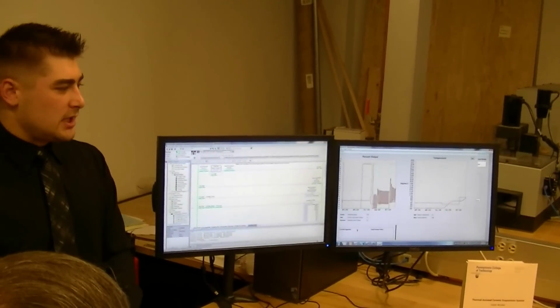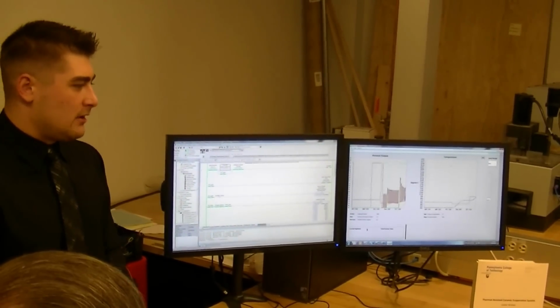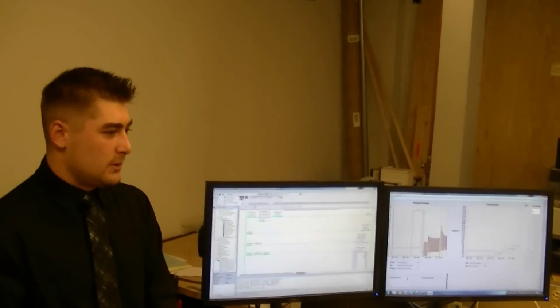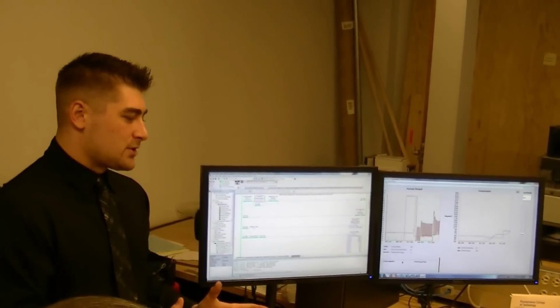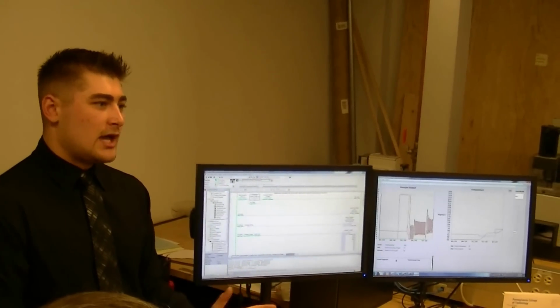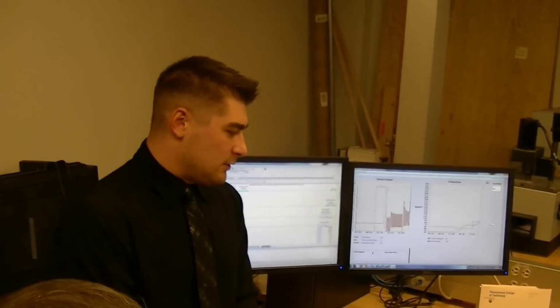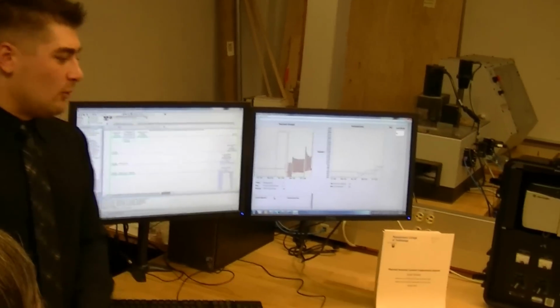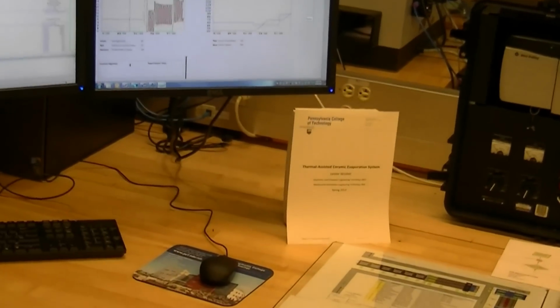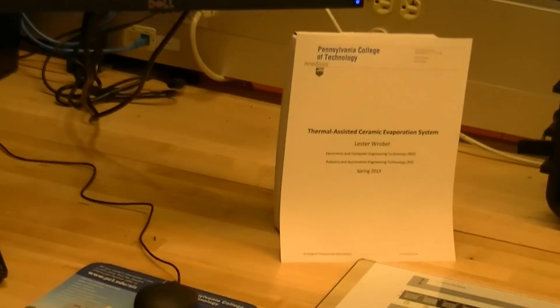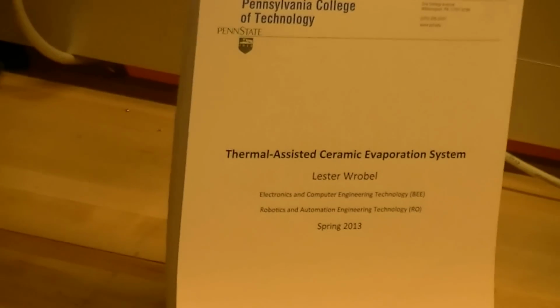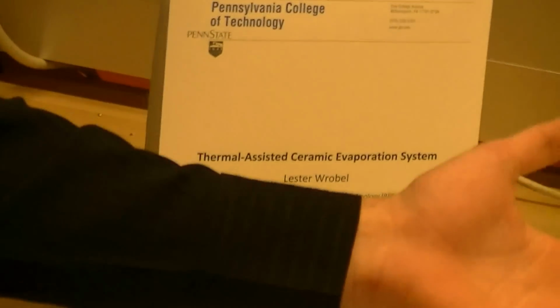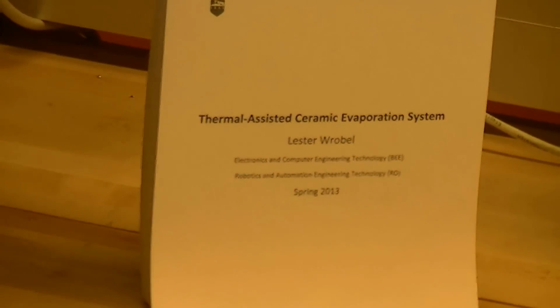We have a little bit of everything in here, and from the ground up, even from the design aspect all the way to the final implementation, every piece is very crucial off of good engineering from the start. As you all know, I'm sure, if you don't have something as simple as a block diagram from the start, you might have someone coming to the system to troubleshoot, and they won't know what the system's supposed to do. Well, having process flowcharts will then show you, okay, the system should behave like this in this condition. Why isn't it? You hand those to an engineer, and he'll be able to interpret that flowchart and translate it into HMI or PLC logic.